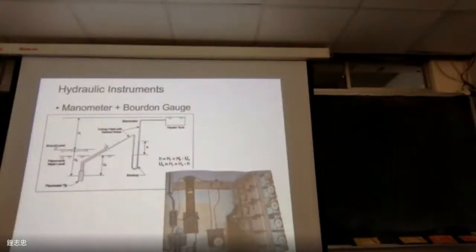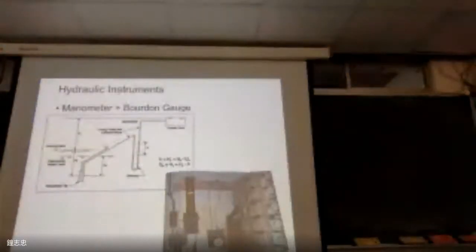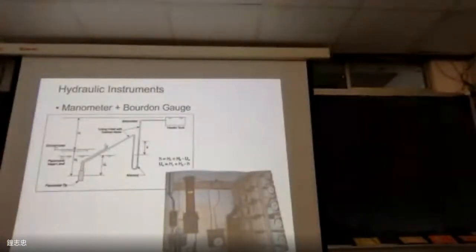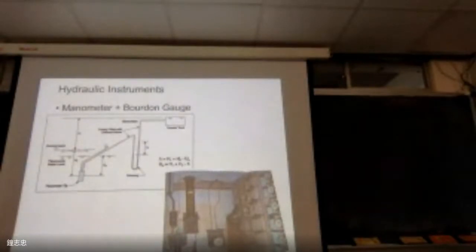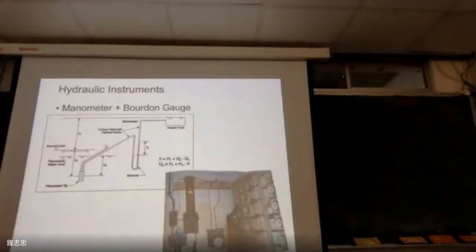Okay, and for the H4, for the normal situation, if this is the water level here, of course there is no response of this sensor because there is no water pressure at all. But however, just as I said, if we have a seepage path for the pipe problem, right now this is an abnormal situation with the water level increased to here. So maybe there's a response of a positive water pressure.